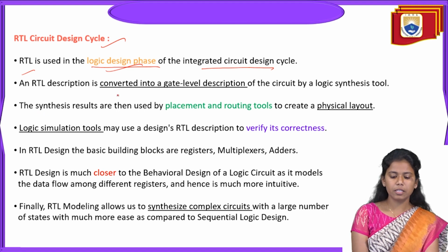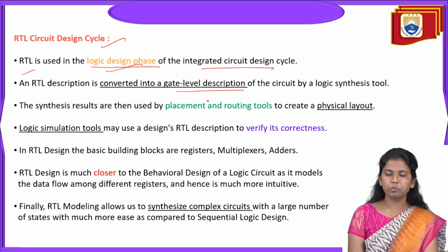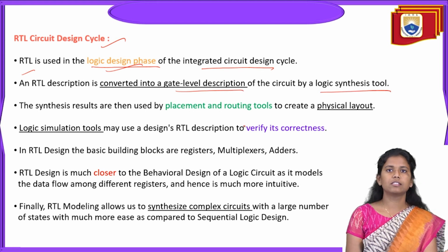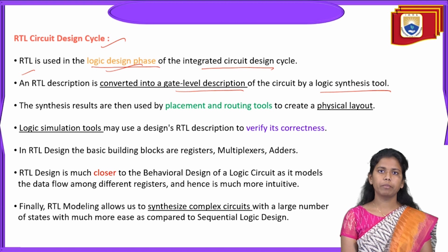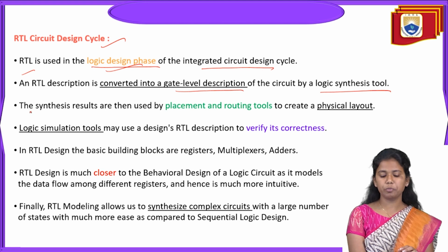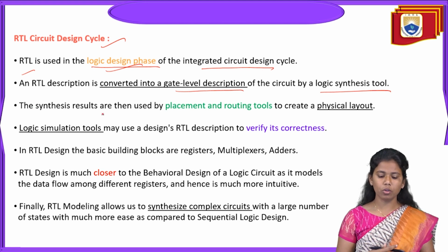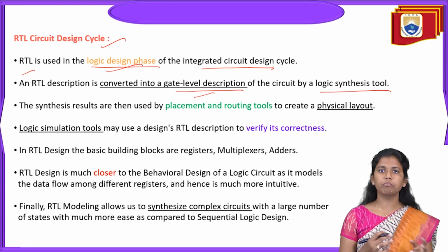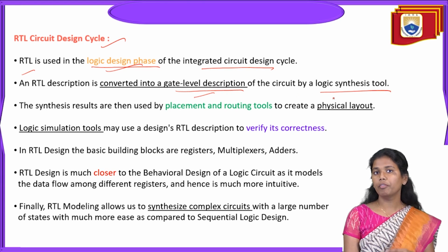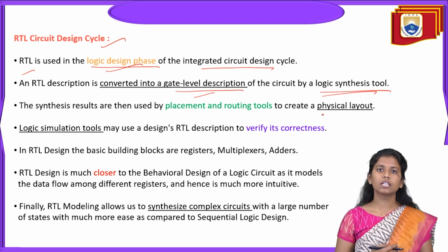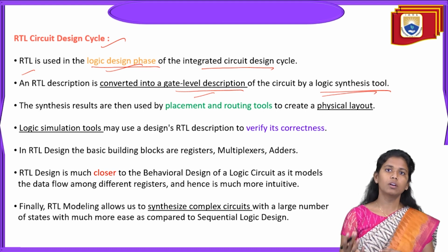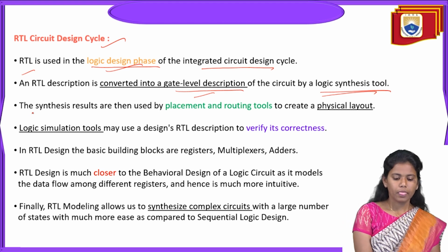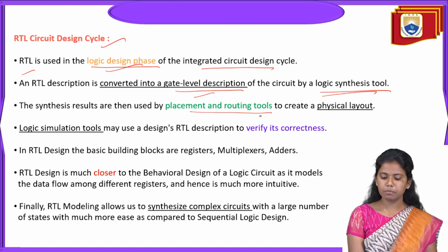And then an RTL description is converted into a gate level description of the circuit by a logical synthesis tool. If you observe this statement, it's talking about conversions, about transformations: if you want to convert the RTL description, from the data flow level, into a gate level description of the circuit, we can use the logical synthesis tool. And then the synthesis results are used by placement and routing tools.